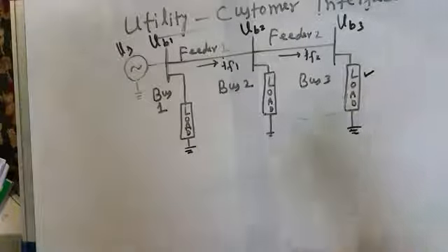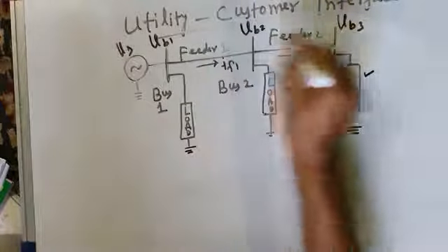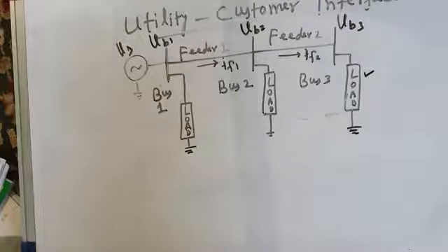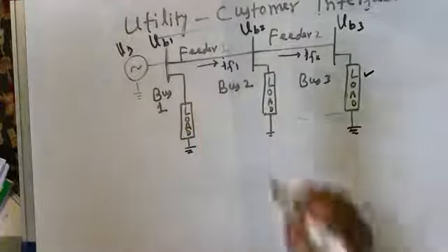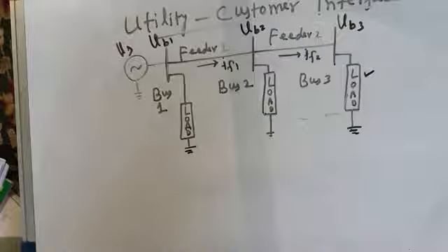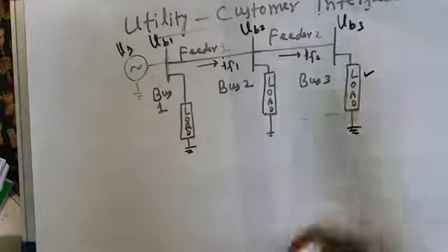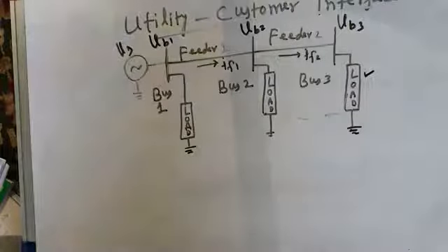It results in three-phase unbalance and hence unbalanced bus voltages. These loads also draw distorted currents, and hence they result in distorted bus voltages. And let us suppose some of these industrial loads also draw power at poor power factor, and hence they result in large I square R loss and voltage drop, and hence voltage regulation of these bus voltages becomes poor. Okay, so therefore these polluting loads which are connected to bus number 3 have to correct their loads.